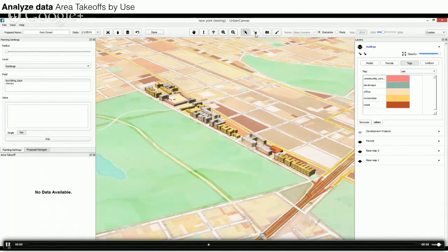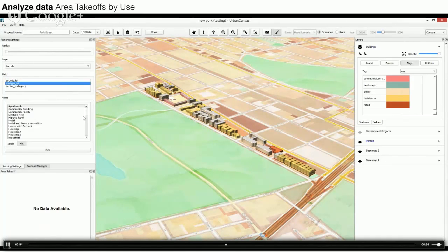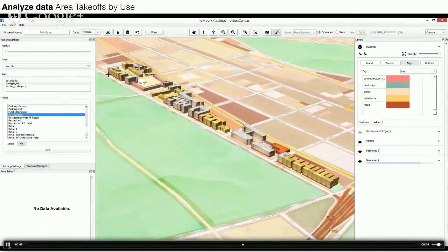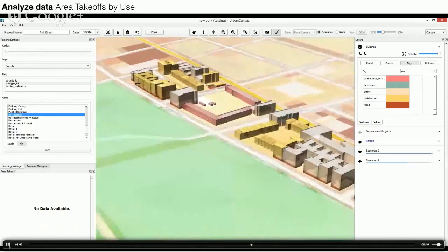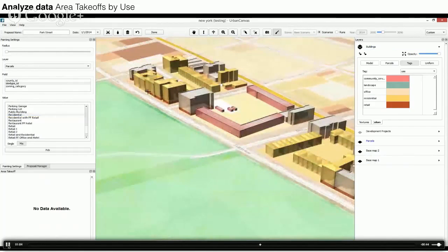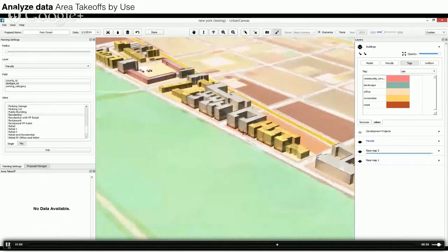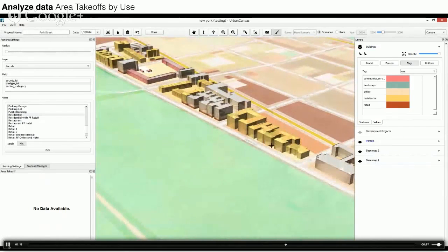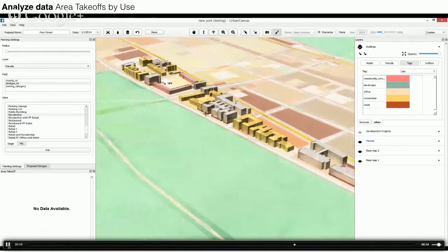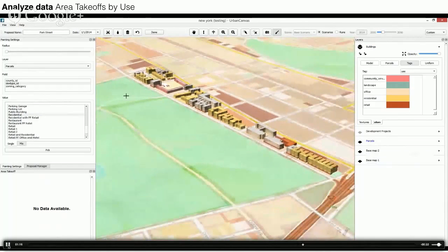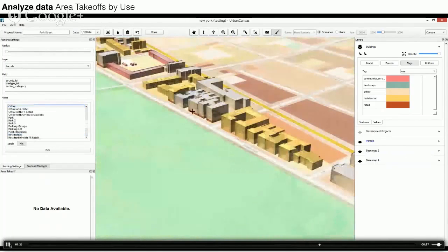So I rework the development types. I use the painting tool on the left here. I pick the parcel as a field, and I pick pure residential as my development type, and I start painting over the residential plus retail type that I created before, and I make it purely residential. So that probably I'll create a cluster of retail on the southern edge of the site, and the rest of it I'll create a mix of offices and residential. So what I would do with office retail type, I'll change it to completely office type.